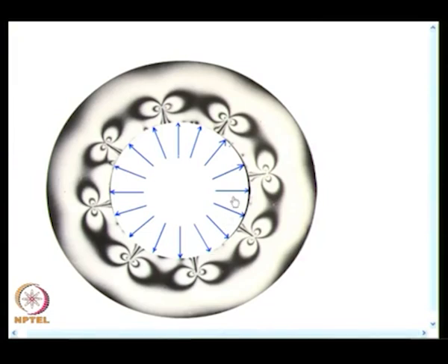And we have also looked in the last class at a series of radial cracks emanating from the inner boundary, and from your understanding of solid mechanics, because it is subject to hoop stress, it is essentially in mode 1 loading, and you observed that there is no major interaction of these cracks. When you have multiple cracks, if they are far apart, they are not really interacting, and you also saw that the fringes depict a typical mode 1 loading situation.